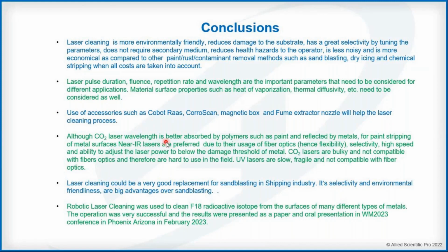We compared the CO2 laser with the near IR laser, and we mentioned that CO2 lasers are inherently safe, but they're bulky and not compatible with fiber optics, and for this reason, it is better to use a near IR laser and tune the parameters than use a CO2.